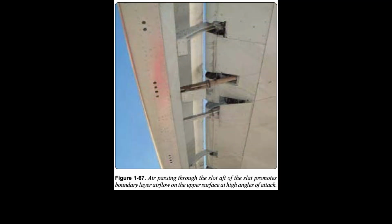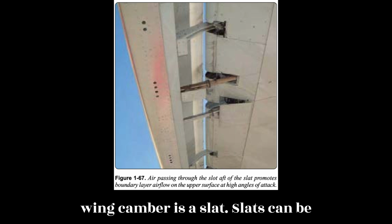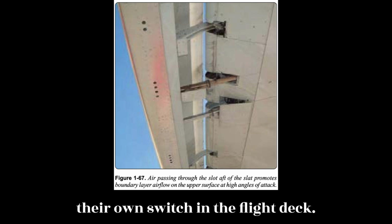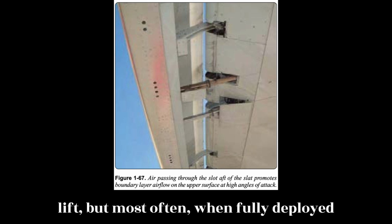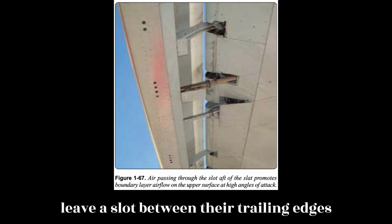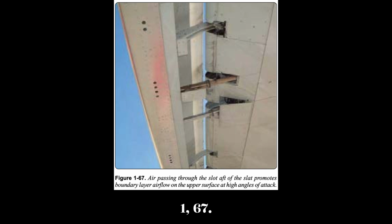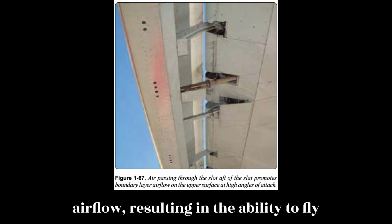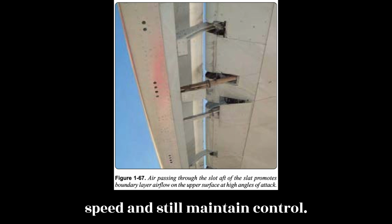Slats. Another leading edge device which extends wing camber is a slat. Slats can be operated independently of the flaps with their own switch in the flight deck. Slats not only extend out of the leading edge of the wing, increasing camber and lift, but most often, when fully deployed, leave a slot between their trailing edges and the leading edge of the wing. Figure 1-67. This increases the angle of attack at which the wing will maintain its laminar airflow, resulting in the ability to fly the aircraft slower with a reduced stall speed, and still maintain control.